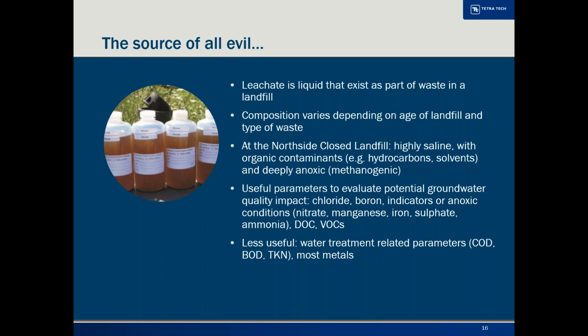Parameters that are always analyzed also according to the standards of landfills in leachate are parameters that I call water treatment related, like chemical oxygen demand and biochemical oxygen demand, total Kjeldahl nitrogen, and metals, and typically they look for total metals. The reason that they do these parameters is that if you truck the leachate off to a treatment plant, they want to know how they have to adjust the treatment and whether some of the metals end up in the treatment sludge and whatnot. But for groundwater analysis, those parameters are not that useful.